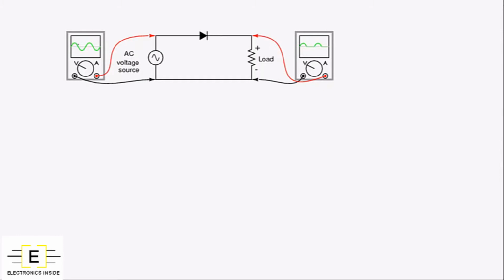You can see here we have the AC signal on the left-hand side connected to the source, and over here it's a DC signal across the load. It's a changing voltage across the load, and therefore a changing current. But you'll see that it never goes below zero, so that current is always in one direction.